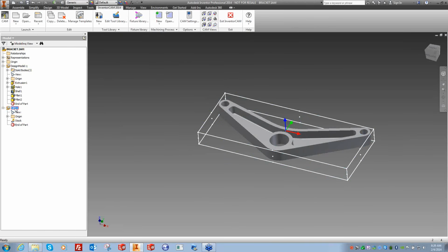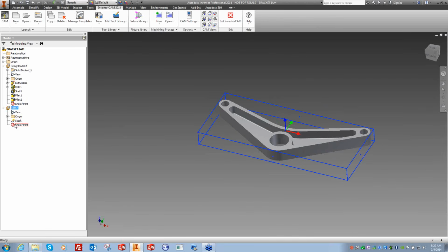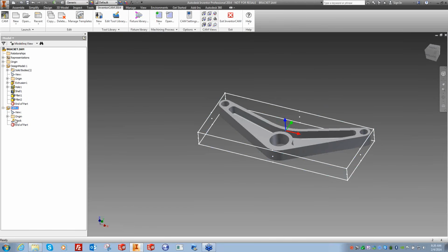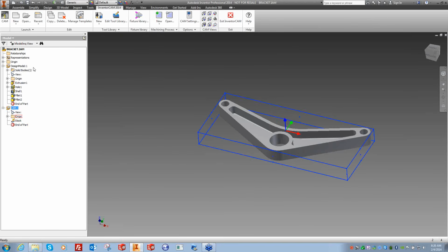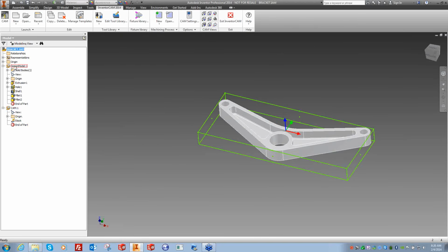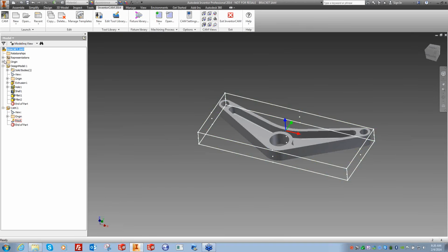So that means if you've built in boundary curves, surfaces, solids, whatever, you're going to want to build them inside the CAM model, or at the assembly level. Don't build them inside the design model because you'll lose those changes. So that's how we handle revisions, and generally that's where we put our stock as well.